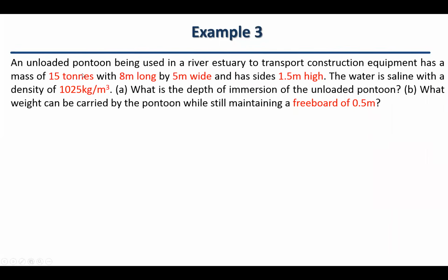We have a situation with an unloaded pontoon, so there is no load on top of it. It is being used in the river estuary to transport construction equipment, and has a mass of 15 tons, 8 meters long by 5 meters wide, with sides 1.5 meters high. The water is saline with a density of 1025 kilograms per cubic meter. The question is to calculate the depth of immersion for the unloaded pontoon.